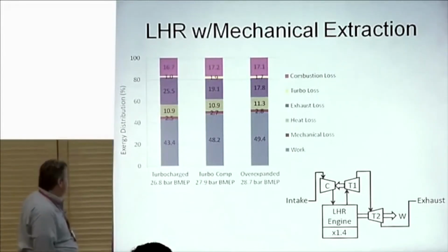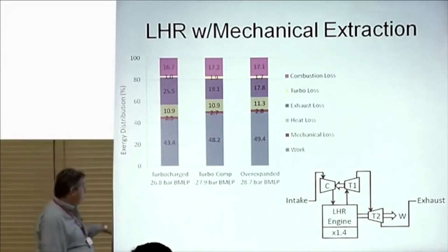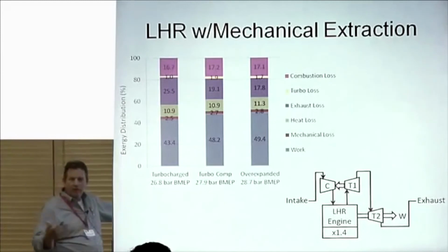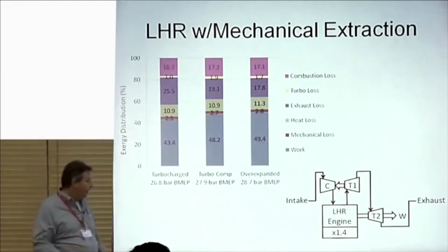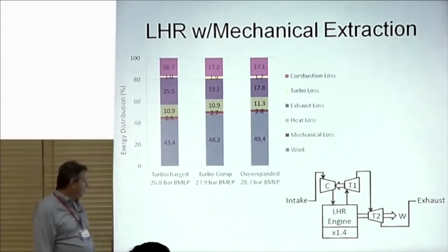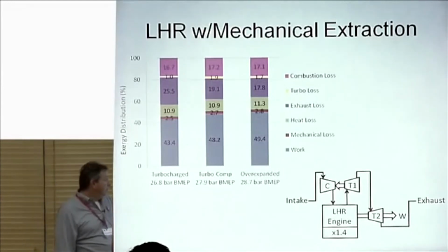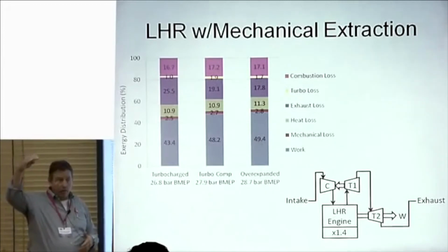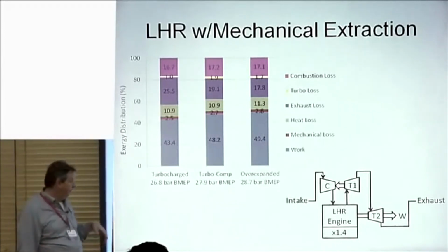And if you do an exergy analysis, it helps you to think about what to do. You want to turbocharge because the head's going to get really hot. Things are going to heat up. You've got to increase the density, keep the power density up. So first, go after a turbocharger. 43% exergy efficiency, so you're higher than that on a lower heating value basis, maybe 45 for that.